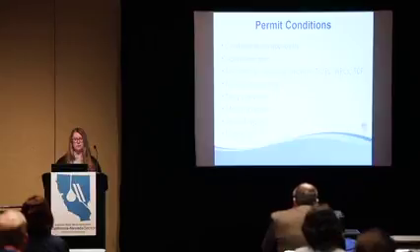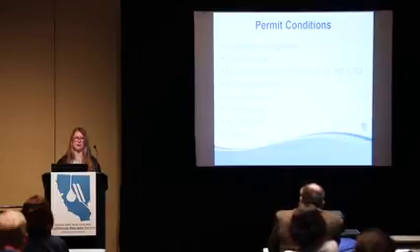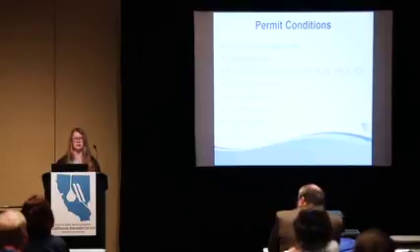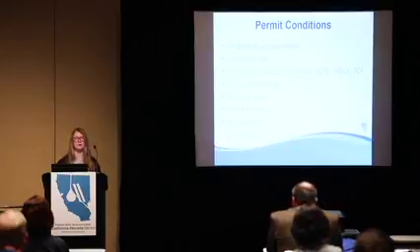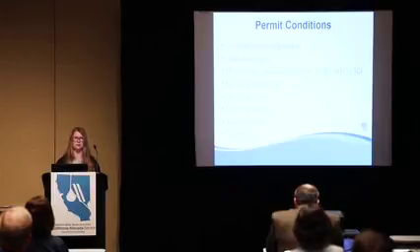One of the important parts of this process is doing the monthly reporting into the Division of Drinking Water, which is required every month. So there was a lot of report design and making sure the right data was showing up on the reports. We started out with a commissioning period, so you have 4 weeks of weekly sampling, and then if everything looks like it's working properly, while it's running the system, you can go to monthly sampling. To get all that data during that 4-week period onto our monthly reports was a challenge, and we made sure we coordinated so that data was on there.